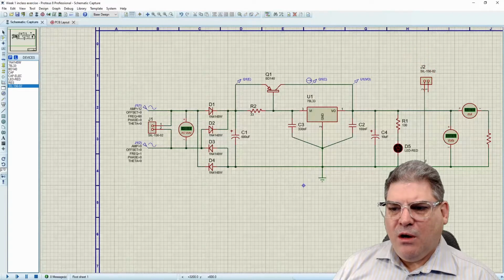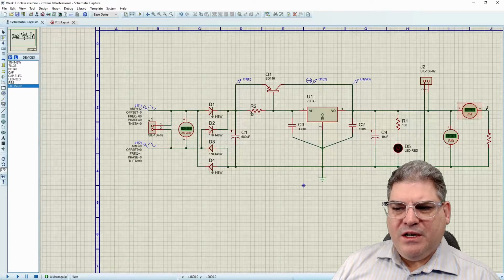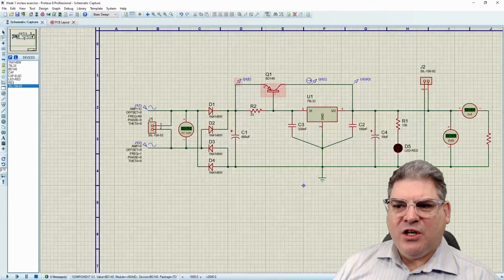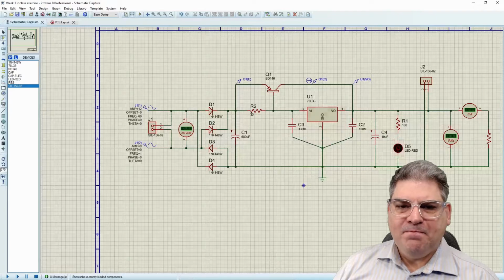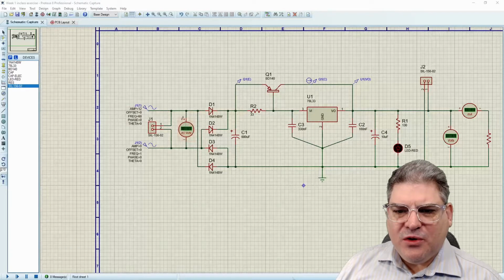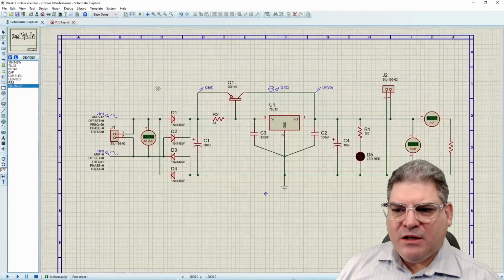Okay, so here we go. I'm going to connect this like so. The reason is if I connect it here, when we go to do our PCB layout, it doesn't know what to deal with this. It will actually exclude it, and this wire would not get connected. So the right place to put it is upstream of this. And remember that this is basically just for our simulation. All of this will be excluded in the PCB layout. Okay, this is fantastic. So this is the first portion of our assignment.